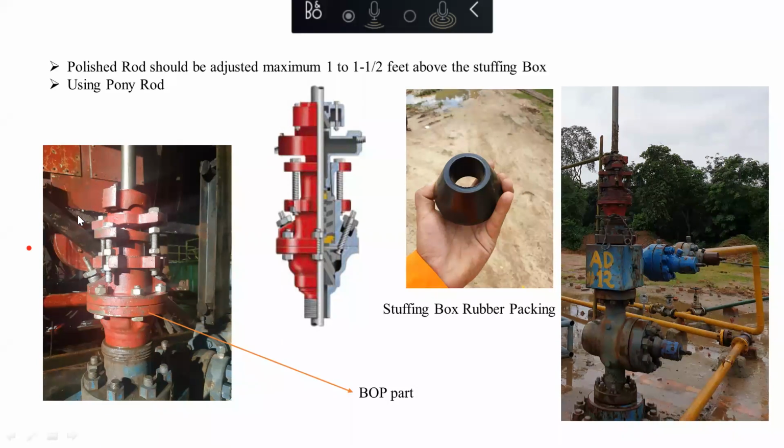If it's not, you are going to circulate your pump, reverse circulation. You will circulate water or your workover fluid from the annulus through the tubing. As I said, your standing valve and traveling valve, the fluids can go upwards but not downwards. So when you tested before installing the stuffing box and the polish rod, the sucker rod, you tested using the forward testing.